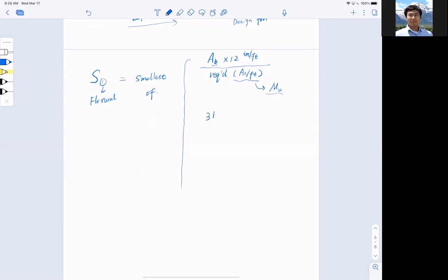And then it has to be 3 HF or 18 inches. And remember, this is the so-called deflection control criteria. And then the last two equations are for cracking, which I have shown you: 40,000 divided by Fs minus 2.5 times concrete clear cover CC, and then 12 times 40,000 again divided by Fs.